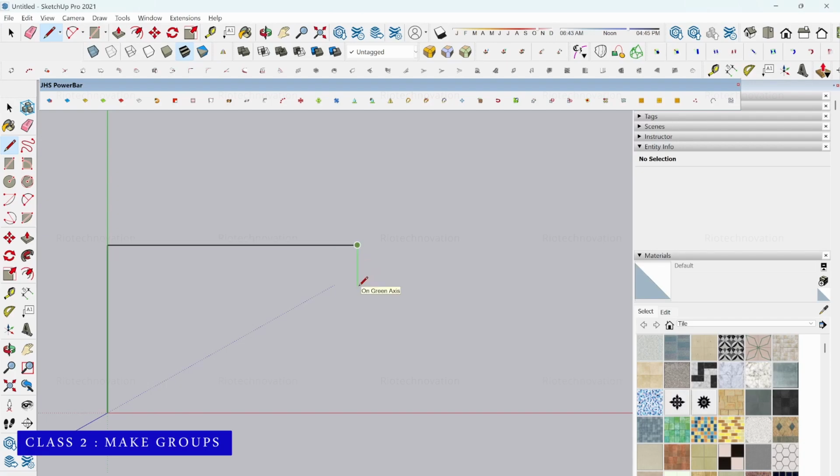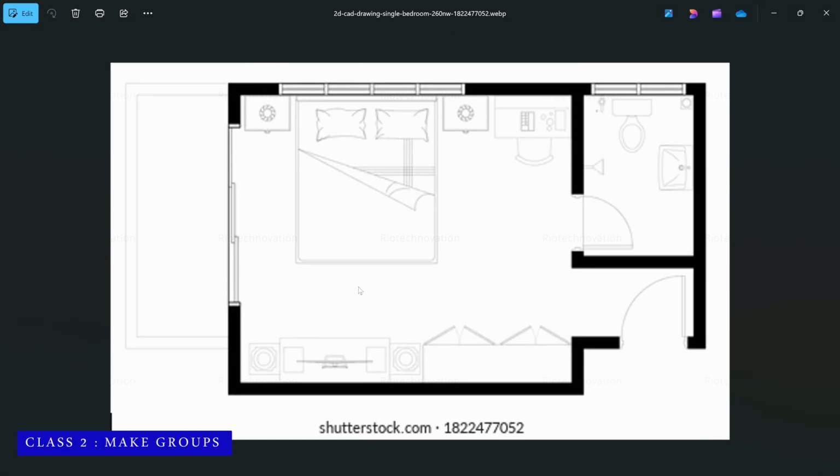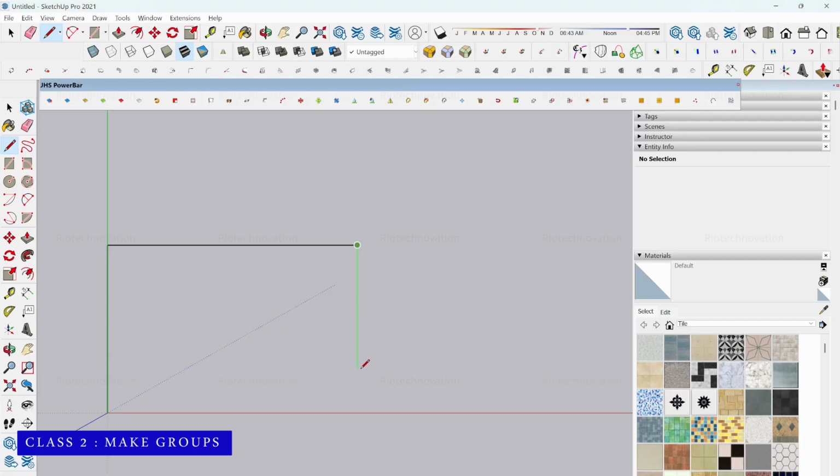So that is it. Then down it is coming. Yeah. So till this point it is coming. Then I'll make an offset of 9 inches. Enter. I'll match this here. Then when I'm coming again, you can see at the right side bottom it is already giving us the measurement, that is 9 inches. So I'll give that. See, I'll click here again. When I'm taking out 9 inches, it is giving, I can match this line. It's very difficult to match, you have to match it. And from outside again 9 inches I will go, I need to watch till which point. Yeah, till this point I will go, and I will make another wall.